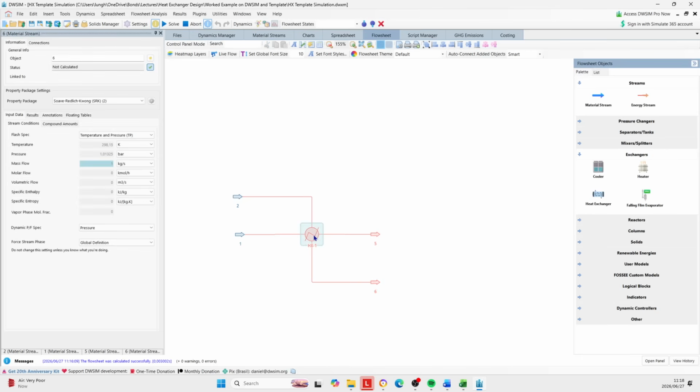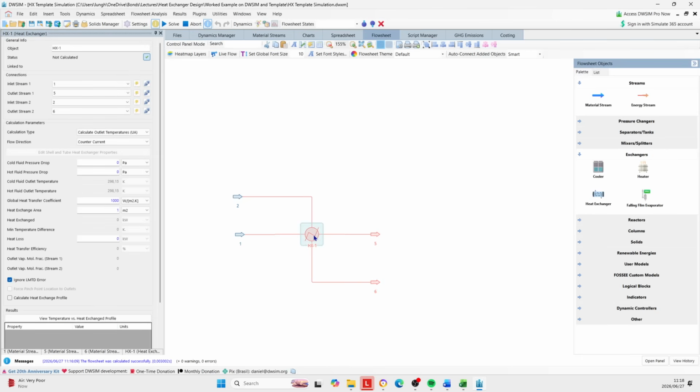So when you click on the exchanger, it will give you these options. Now these options are what you want to do with the exchanger. So I'm going to go with counter current. I love counter current. Go read up about its advantages, especially the students. It allows you to circumvent the idea of approach temperature, where your cooling stream can have a crossover in terms of temperatures, whereas in co-current you cannot have that. Okay, so what are we trying to do?